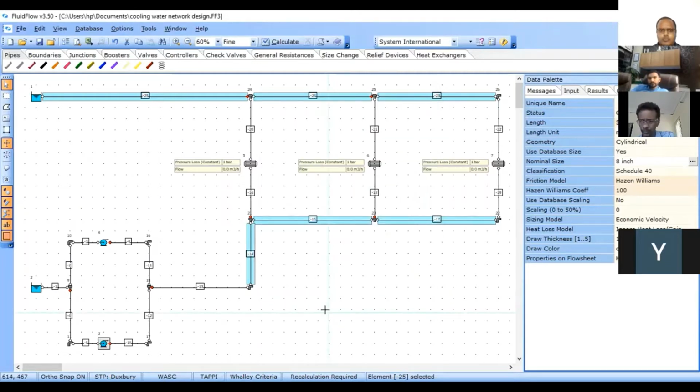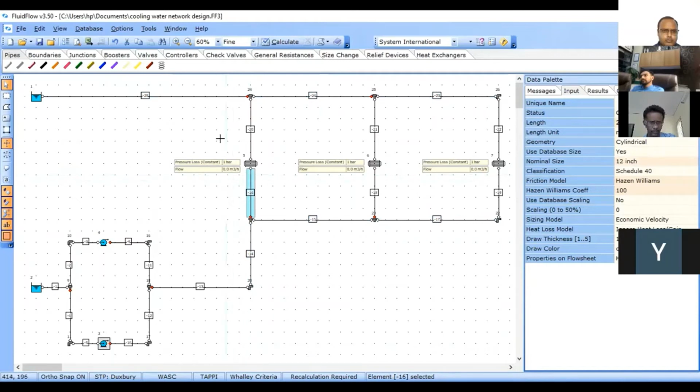Okay. All right. Now there are total 6 pipe segments around the exchanger, inlet to exchanger and outlet from the exchanger. So please select those 6 pipes. The heat exchanger, inlet and outlets. Yes, correct. Using the shift key. Okay. So this will be 10 meters and 5-inch, schedule 40.